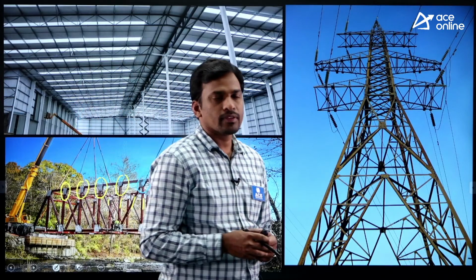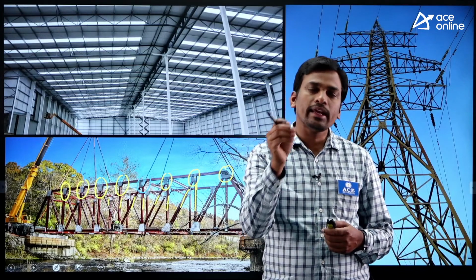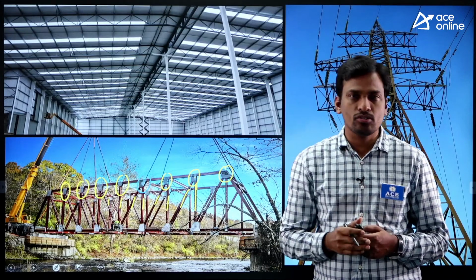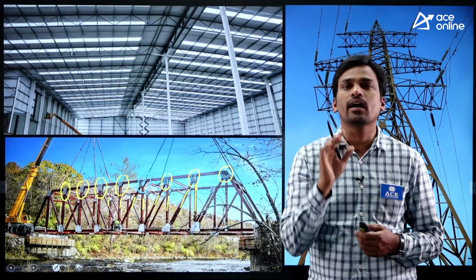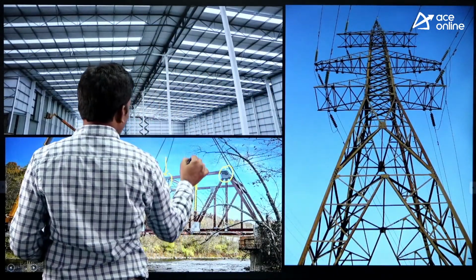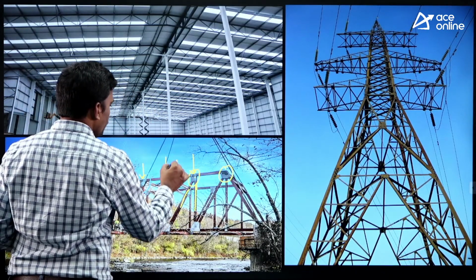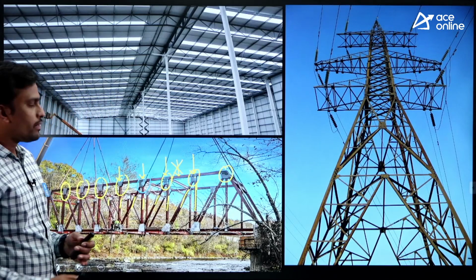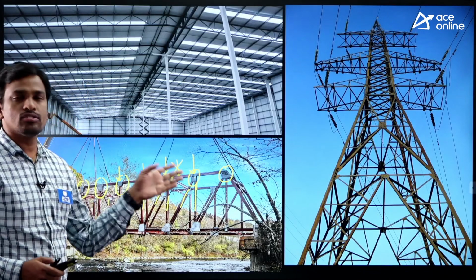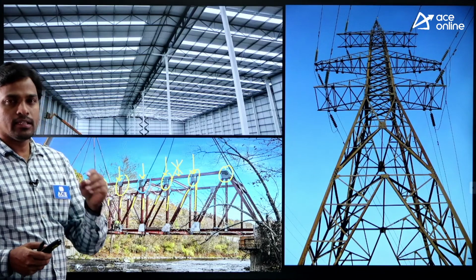And third condition, in trusses, loads should act only at the joints. Loads will not act between the joints. It means load will not act on the member. Always in the trusses, loads will act only at the joints, not between the joints. If the load acts on the member, then it is not called a truss, it is called a rigid jointed frame only. So these are the three conditions to identify the given frame.